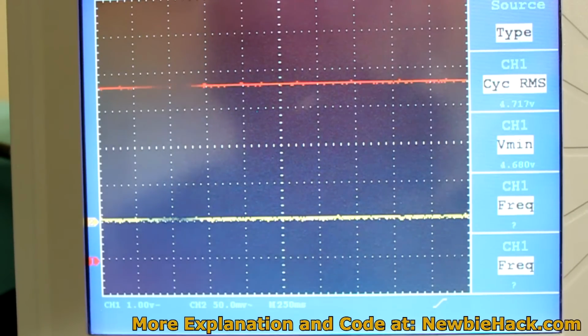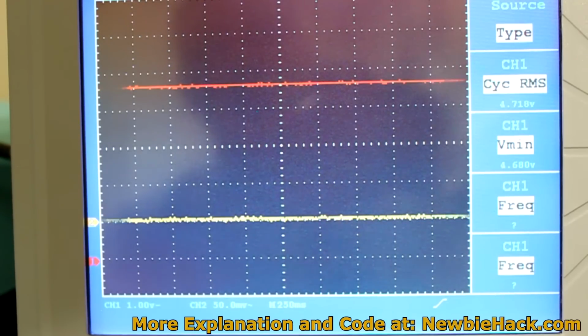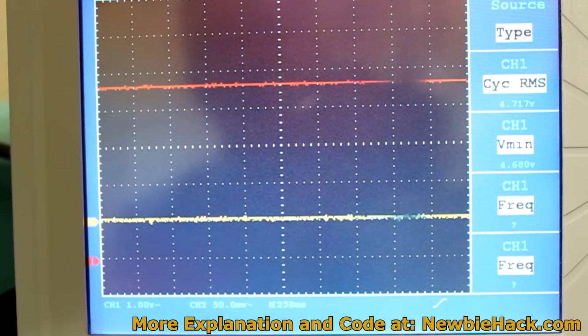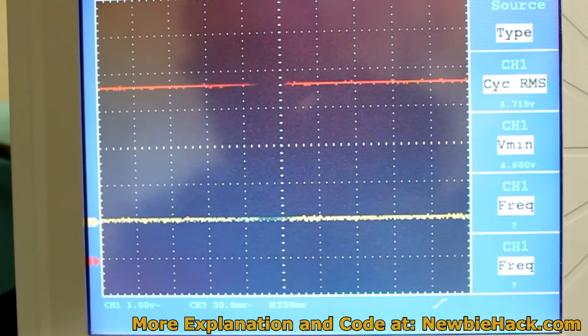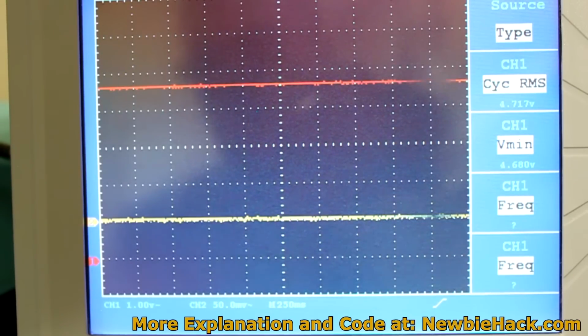We also found out from the voltages how we will apply it to the microcontroller. When we get into the microcontroller and start to do the ADC, we can use a real gauge to find out what the actual inches of mercury or psi or whatever is, to determine the conversion we need to do, or the algorithm we need to do in the microcontroller to show the correct value on the LCD.